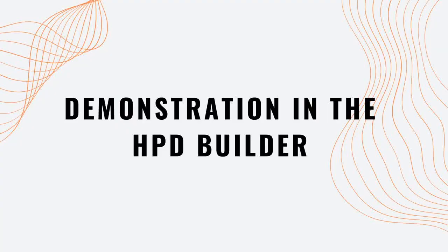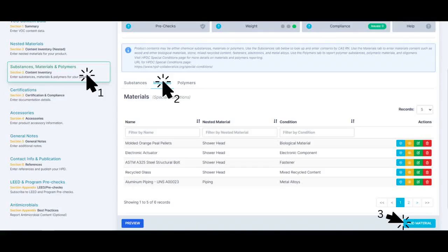In this section, we will show you a step-by-step process of how to comply with this special condition and end with a live demonstration of how to use the mixed recycled content special condition in the HPD builder. To start, fill out the general information, VOC content data, and add your nested materials or product information like you would for any other HPD. To enter a special condition, first click on the Substances, Materials, and Polymers tab on the left. Second, click on the Materials tab, which is where you can enter the special condition. Third, click Add Material in the bottom right corner.